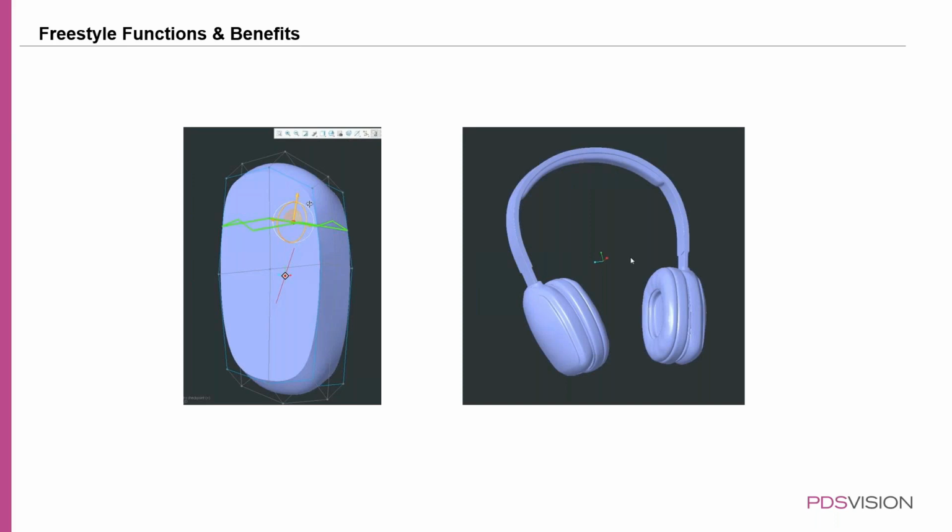And then from here, you can take it into Keyshot, and it could be directly tied to each other. It's connected. There is a Keyshot plugin for Creo, so if you ever have to go back and change the design and the model, you can update it in Creo and it will cross over to Keyshot. Within Keyshot, you can apply your materials, your lighting scenes, as well as render it out. You could even create simple animations that could be quite effective for marketing purposes.